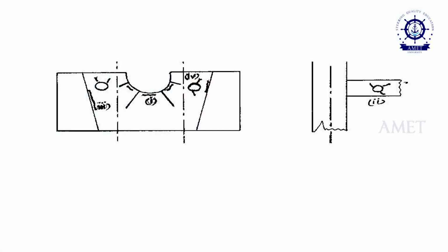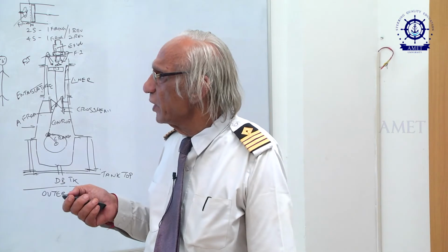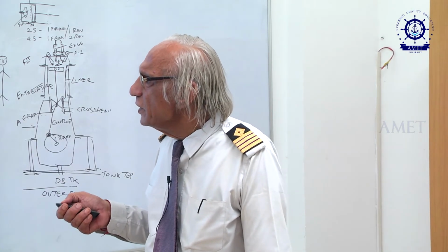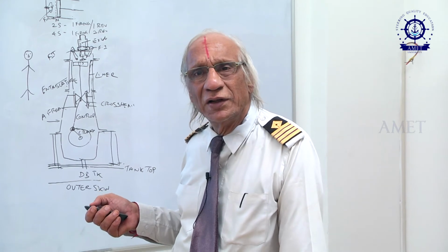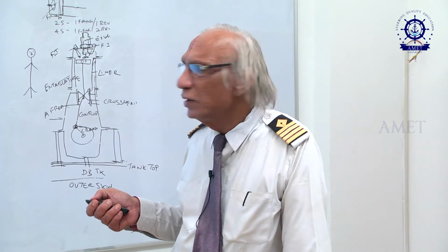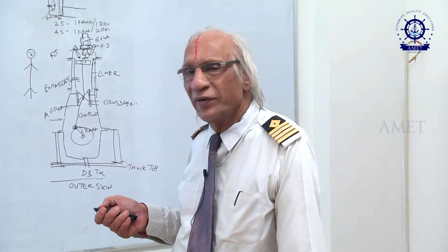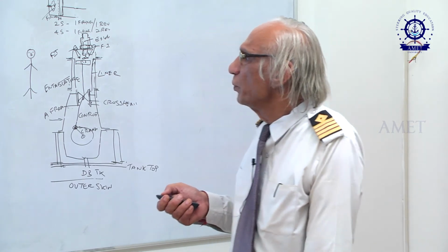So, this is a common defect, and one of the advantages of this fabricated mild steel bed plate is that it can be easily repaired after cleaning, by welding. The only thing is, welders should possess a high quality of skill. That is the most important thing.